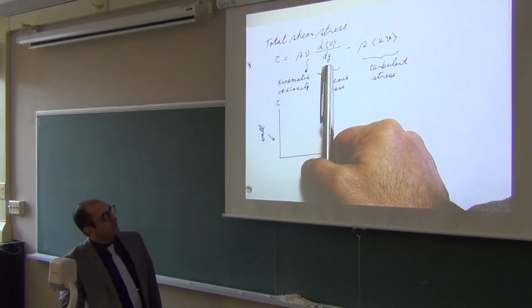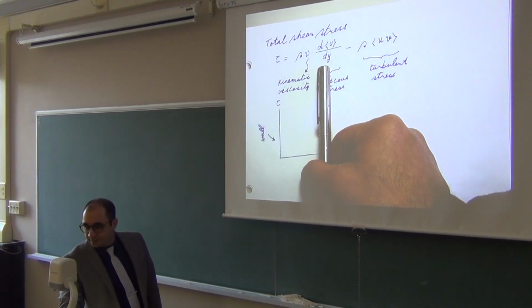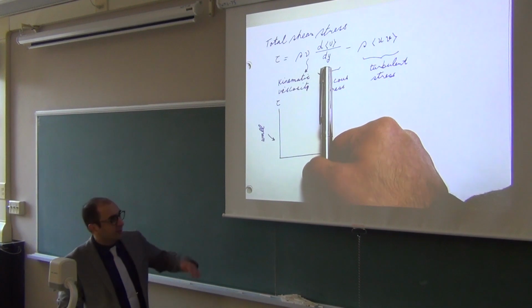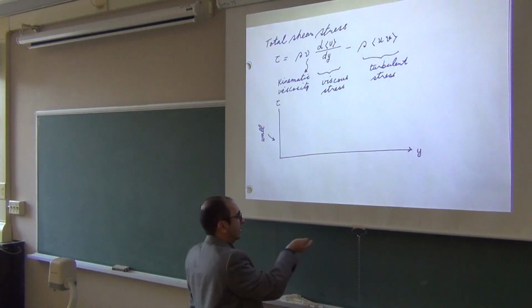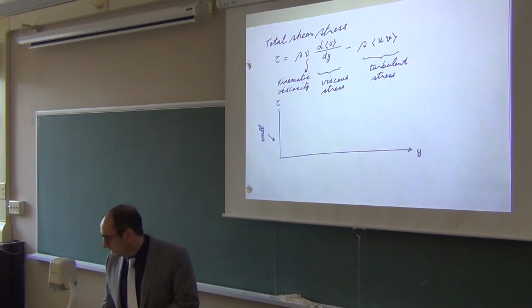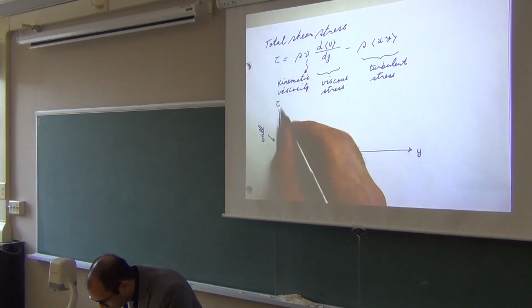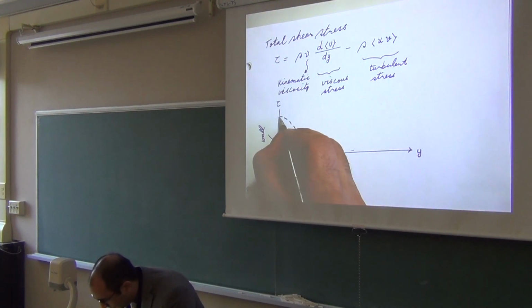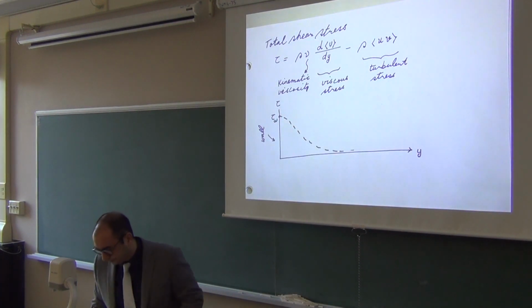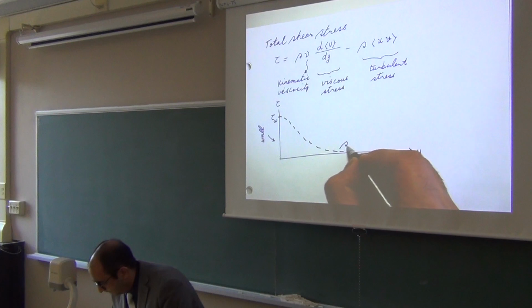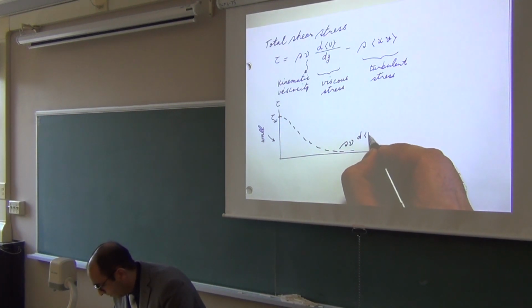the gradient of mean velocity is gradually lost, which means very far away from the wall there won't be any gradient, there won't be any viscous action on slowing down. And that's given by the profile of the mean velocity, right? First the gradient is very sharp, and then it sort of approaches u naught, or the free stream velocity. So somehow I know that the first term eventually disappears. Well, I started at the wall, tau wall. Now, it's pretty interesting. So this term eventually disappears away from the wall.